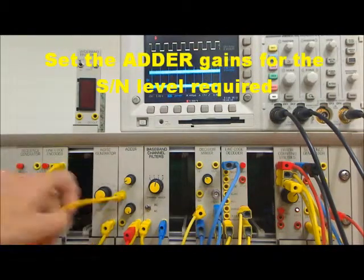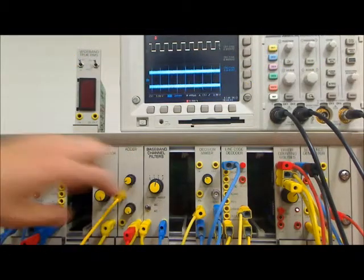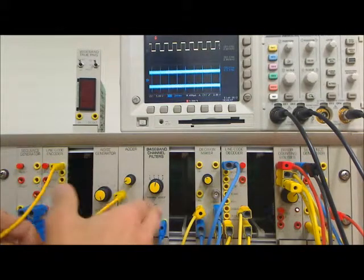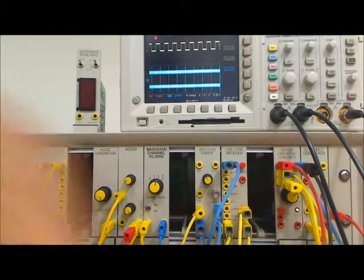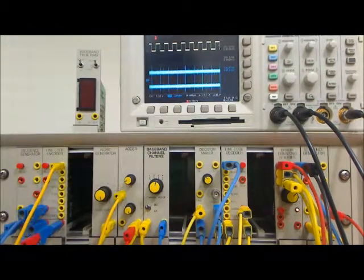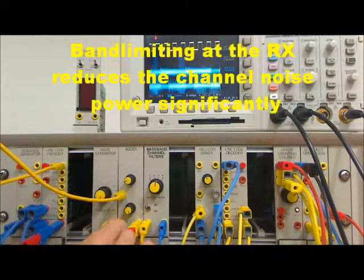I've set the noise generator to a mid-level of plus 14 dB. The gain at the adder is set to maximum, so we have the maximum level of noise going into the adder, and we have a minimal amount of signal going into the adder. The reason we need a high level of noise coming into the channel is because the baseband channel filter eliminates so much of the power of the noise that there's very little noise power left.